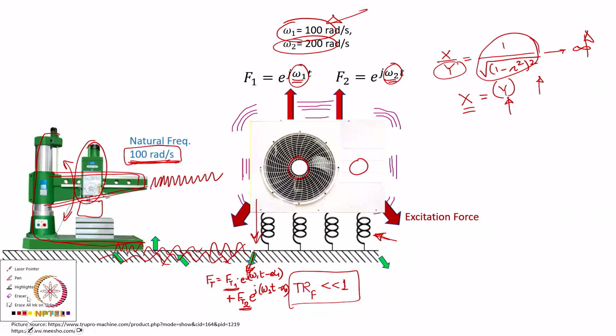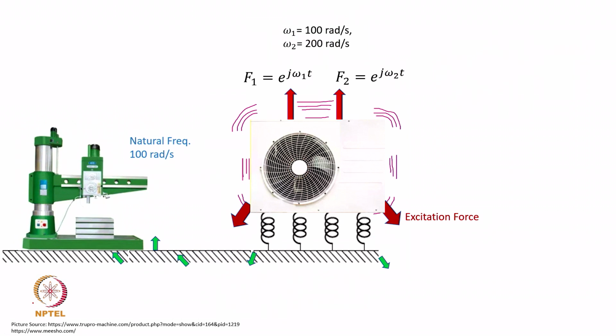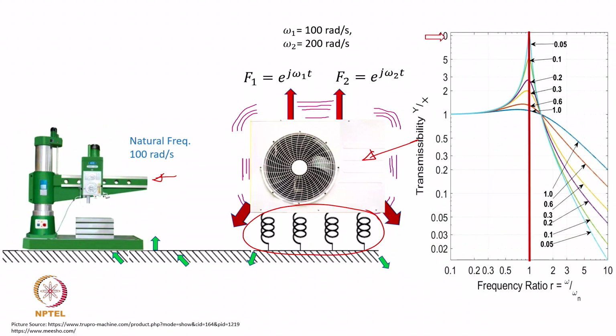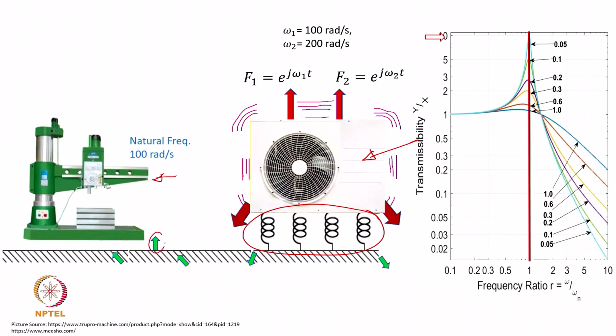So, the point here is you still need to take care of the base excitation as well. You have already taken care of the force transmissibility by properly designing the isolators of the source machine here, but your target machine already has a problem, and therefore I will have to redesign so that this excitation amplitude does not cause larger amplitudes in the target machine.